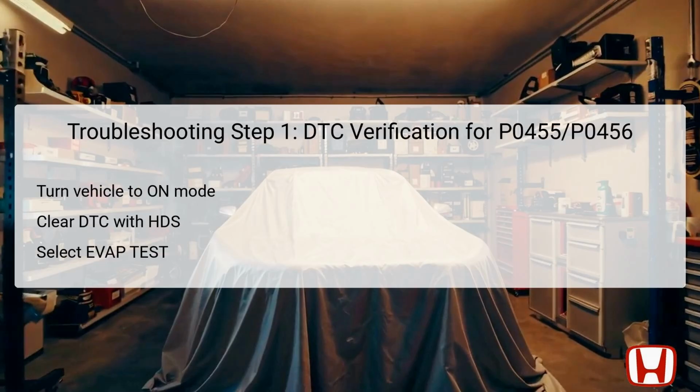In the first troubleshooting step for diagnosing DTC P0455 or P0456, you begin by turning the vehicle to the on mode without starting the engine. This prepares the vehicle's electrical system for diagnostics. Next, utilize the Honda Diagnostic System, HDS, to clear any existing DTCs.